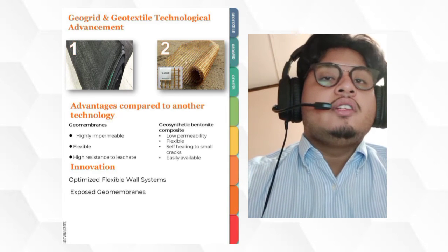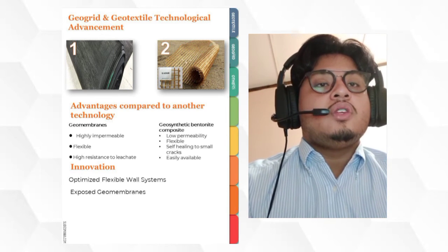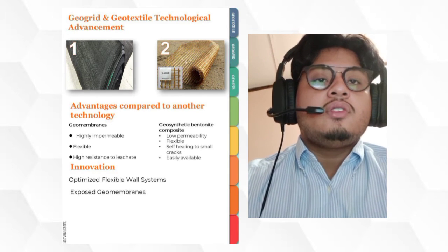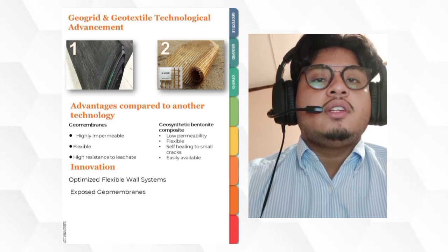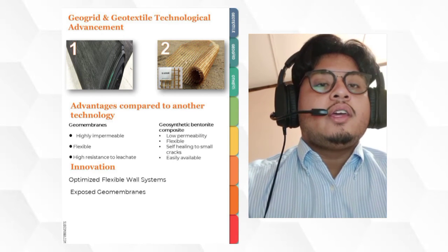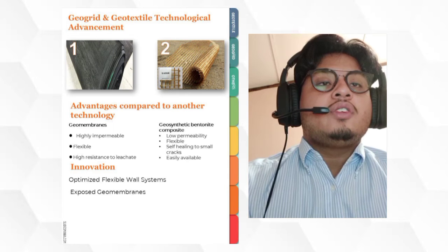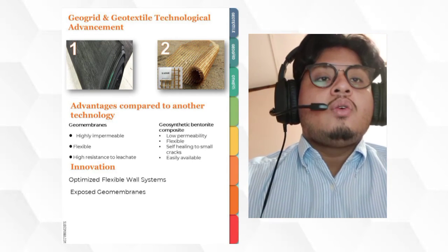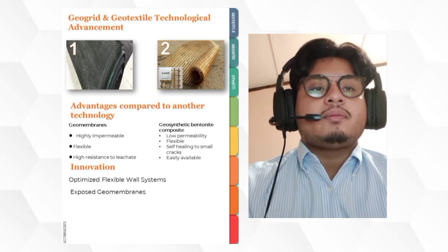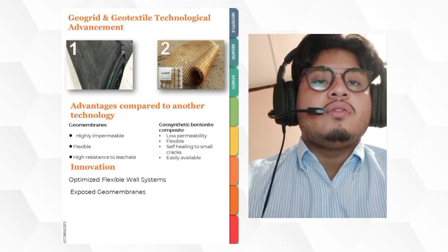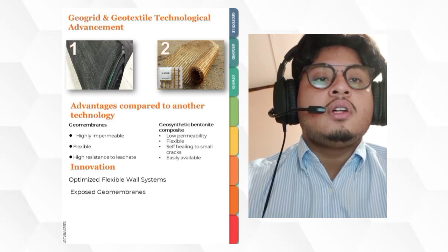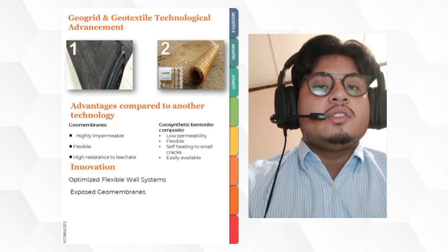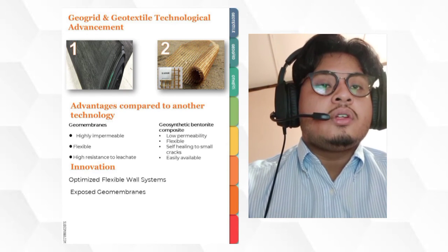Okay, it means that geosynthetic reinforced soil walls involve the use of continuous geosynthetic inclusions such as geogrids and geotextiles. The acceptance of geosynthetics in reinforced soil construction has been triggered by a number of factors, including aesthetics, reliability, simple construction techniques, good seismic performance, and the ability to tolerate large deformation without structural distress. Then, recent advances in the design of geosynthetic reinforced walls and the availability of high strength products have led to systems that are particularly suitable for high walls.